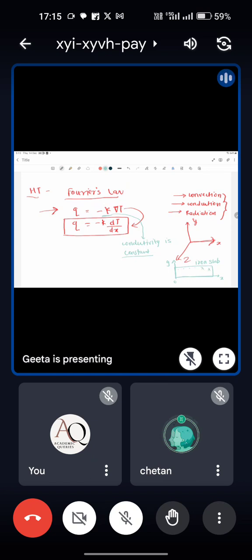That's why it is outside of the gradient term. If it varies with x, suppose at 0.5x it is something different and at 1x it is something different, then you have to consider the conductivity inside the gradient term. Then you can write it as minus del dot k del T. This is a dot product, the dot product of the gradient. Now you tell me one thing, why is it negative?